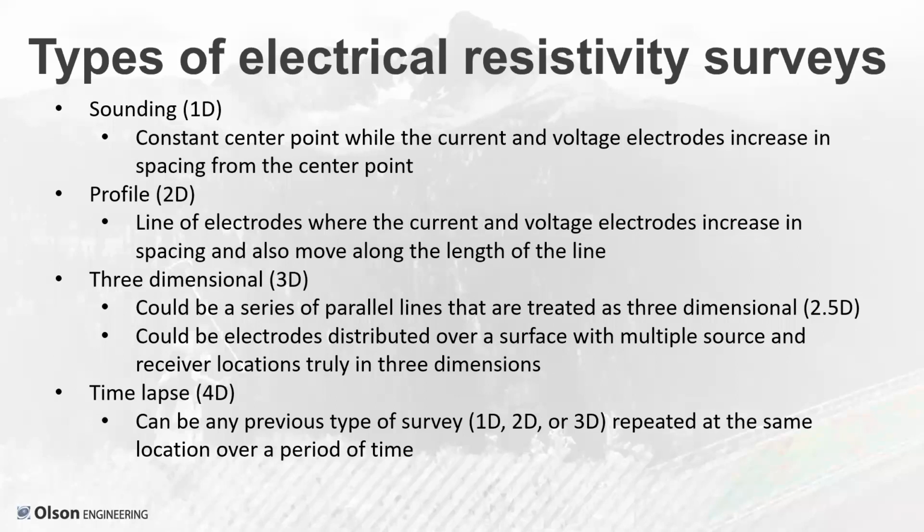But for dams and levees, actually one of the most powerful approaches that can be taken is a time-lapse 4D resistivity survey. And it can be any of the previous types, 1D, 2D, 3D. It's just repeating the exact same survey at the same location over a period of time. And so I've worked on a number of projects in the past where we were worried about anomalous seepage, and that seepage was a function of the season.